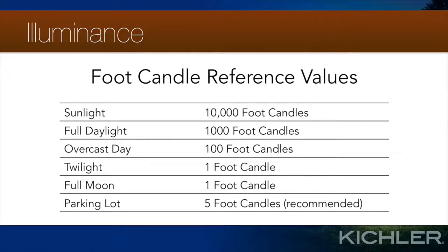The place to have 5 or more foot candles of light are the critical points on paths or walkways, like turns in the path, steps, and landings, focal points, and at the base of large objects like trees, so that you achieve 1.5 foot candles of illuminance at the edges of the object.